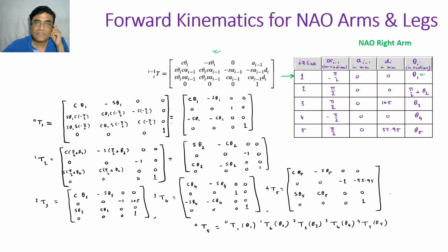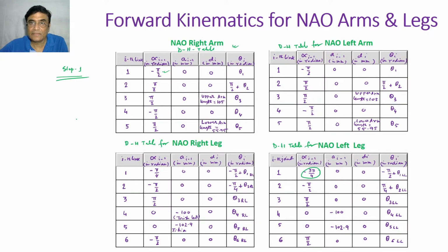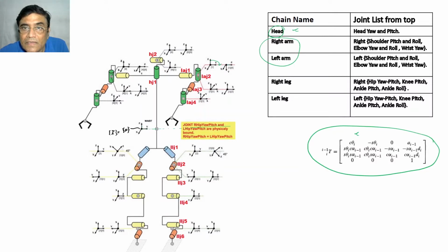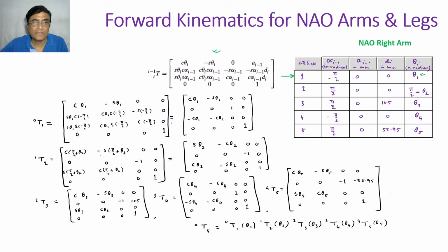So that's how the first row works. You are calculating the transformation matrix of link 1 with respect to the ground link, which is put somewhere here. It is shown here. So the 0th link. Now come to the second row of this matrix. First row is this.